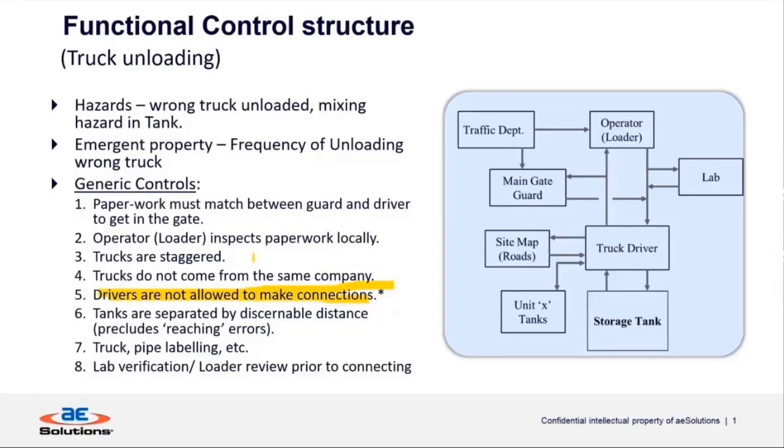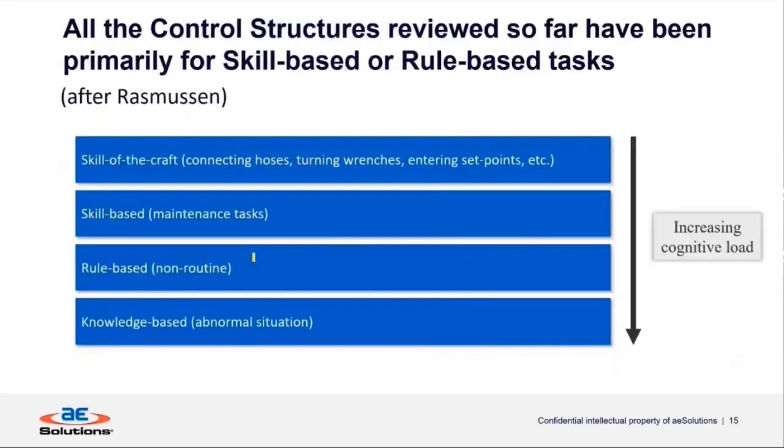The other part of this was they were having trucks lost. It was such a large site, they were having trucks lost frequently, almost every day. And so this was a significant weakness identified that you definitely wouldn't find in a PHA for the individual units, because you're not taking that larger systems view. So this is another example of that systems look, that STPA type look can be valuable.